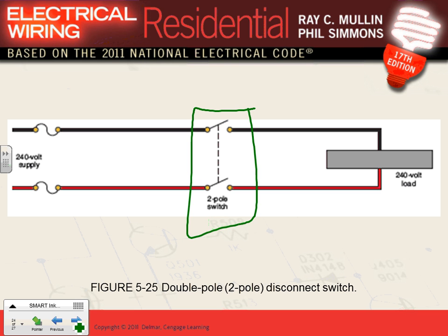When would you use that one? You would use it, my friend, on any fixture you're burning at 240. In residential, the only place where you probably end up using it is if you want to turn on baseboard heaters. They don't use this technology, but they use a thermostat. It has a switch at the end, and actually a thermostat has 2 terminals in, 2 terminals out.